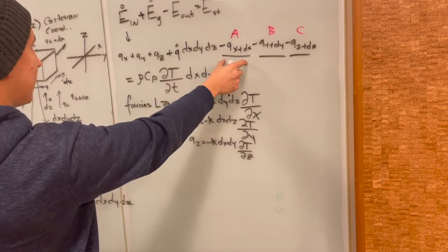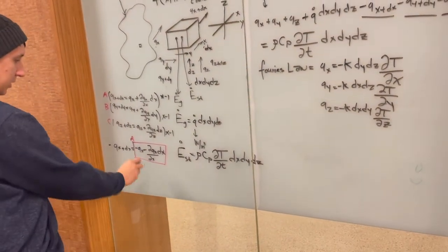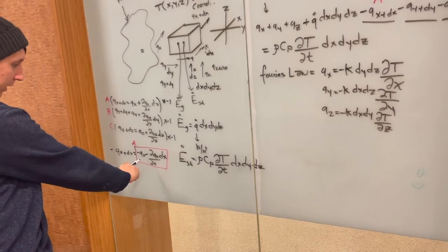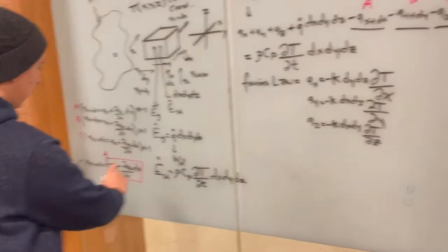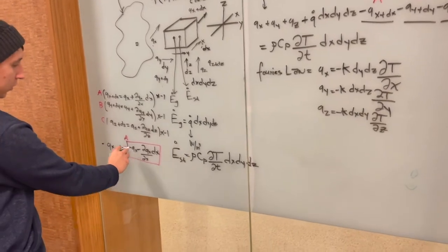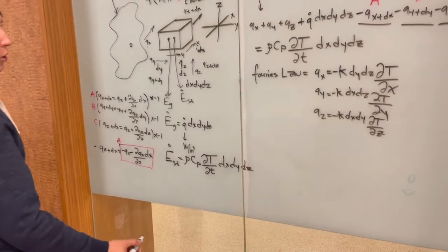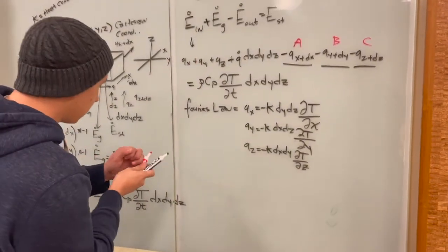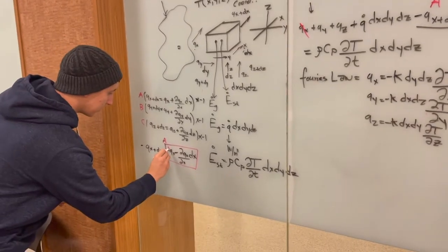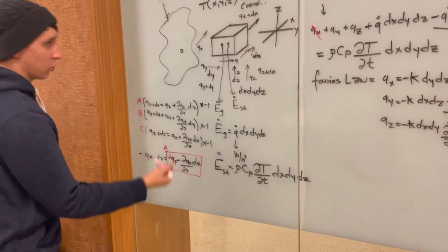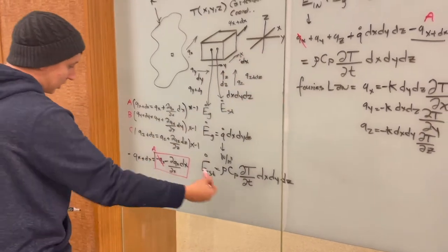if you see this negative qx, this negative qx is going to be replacing here, and it's going to be minus this right here, this change in the heat with respect to the x direction times dx. That's going to be only minus it, so it's not going to be part of the whole entire equation. They're not being multiplied together. So what you're going to notice is that this x right here will cancel out with this one, because it will be qx positive minus qx.